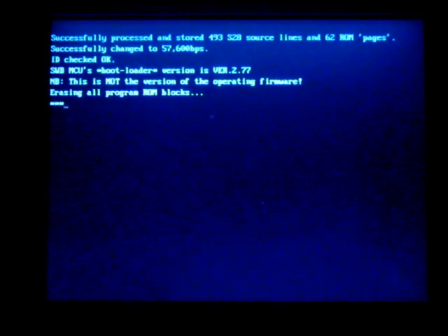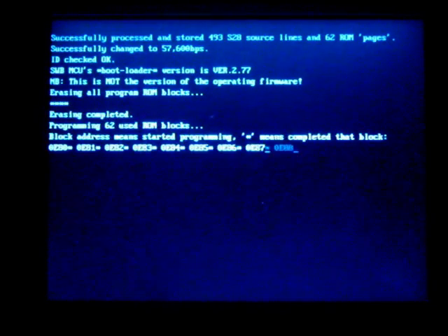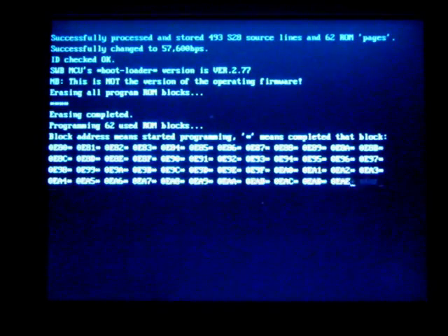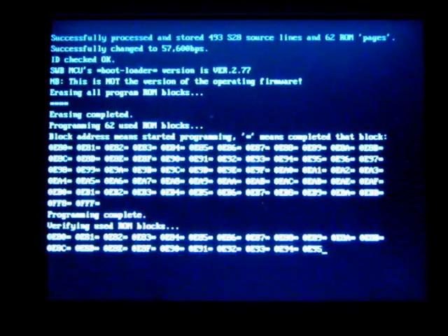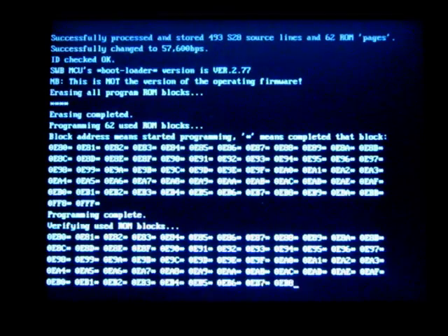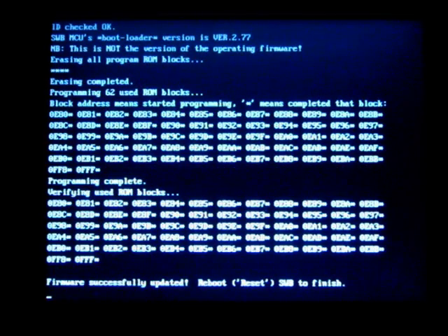From there, the touch PC runs a boot loading routine, transferring the program to the Switchbox and then checking that it was successfully burned to the Switchbox's flash memory. This display is in real time. It doesn't take long, since the whole Switchbox firmware is only about 12 kilobytes.